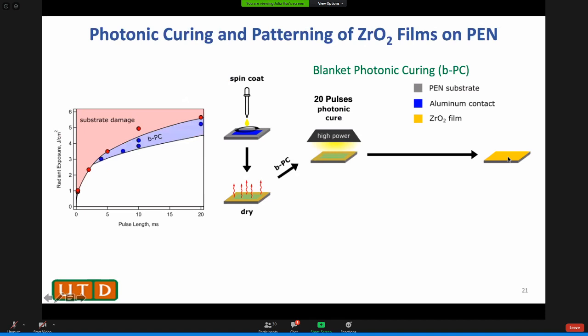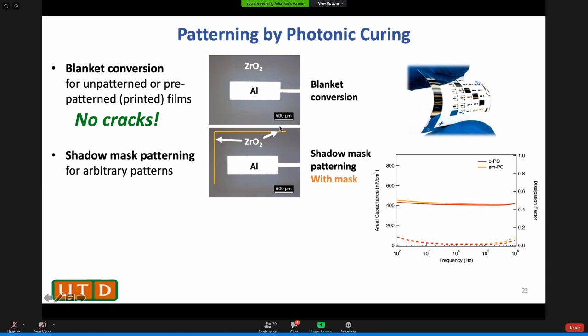And if we use a shadow mask, I draw for you where the edge of zirconium oxide is. And if you have really good eyes, you can see the bottom edge as well. So this has a shadow mask to put down the zirconium oxide. And the CF is about the same. And this is the self-align, which we only have zirconium oxide around the aluminum. And this is low power, and you get the same CF.